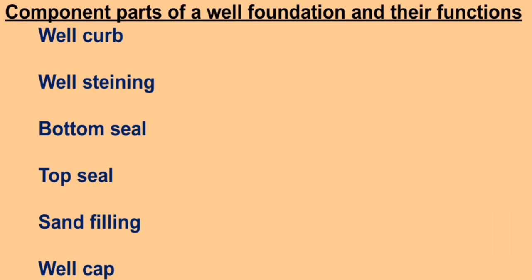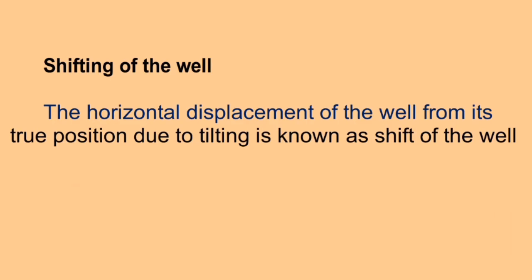Sixth one, well cap. The RCC slab provided over a single or number of wells to support the abutment or pier is called well cap. The function of well cap is to transfer the loads and moments from the pier to the well or wells sunk below the cap. Shifting of the well. The horizontal displacement of the well from its true position due to tilting is known as shift of the well.